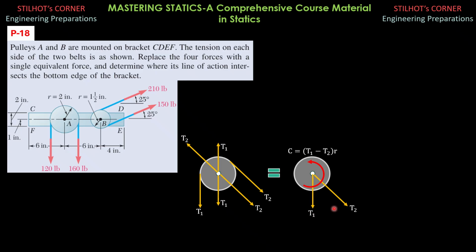So this original system can now be simplified further into this case where we have two tensions at the center and no more couple because the condition is T1 equals T2. So that's the principle, and I hope that you can remember this because in statics there are many force systems, structures that are subjected to pulley systems, and that's the idea on how to manage them.